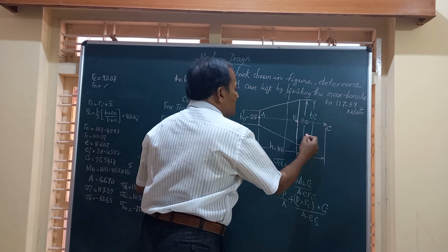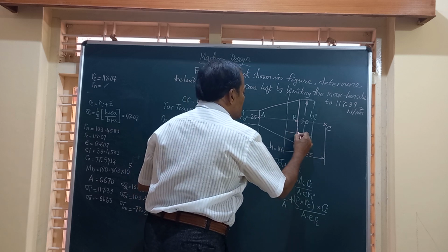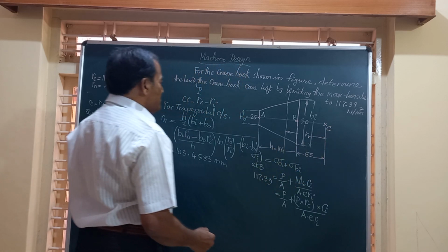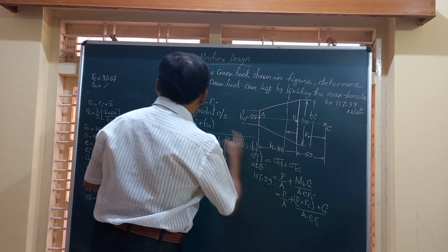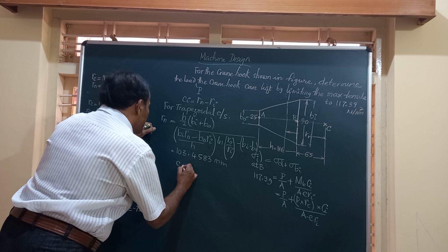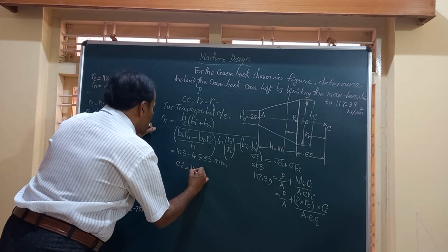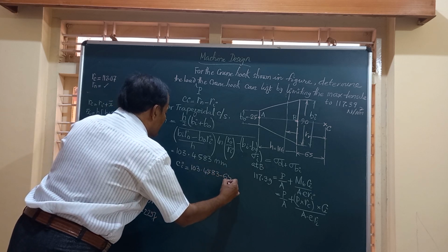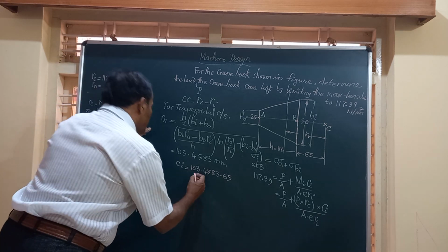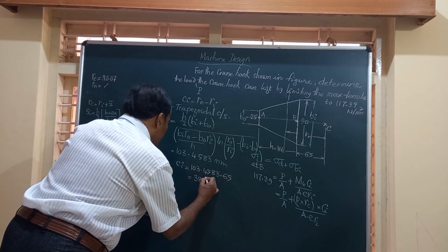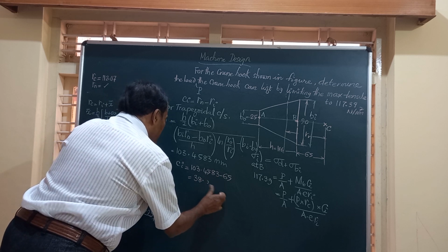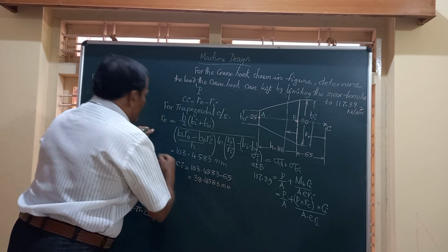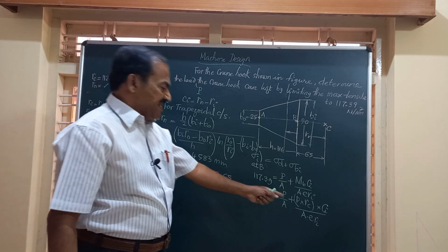This is Rn. Rn is the distance from the neutral axis to the center of curvature C. Then friends, you have to find out the value of Ci. So Ci can be found out now. Therefore friends, Ci is equal to 103.458, that is Rn minus Ra is 65. So this works out to 38.4583 mm. So we did not find out the value of this C naught because we don't need them.